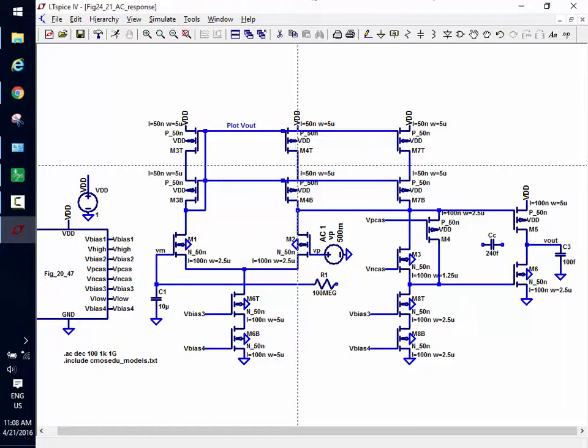No one's going to turn in this topology, right? Okay. So does everybody see sources tied together in both of these? Gates tied together, drains tied together. Sources tied together, gates tied together, drains tied together. Does everybody see that I have a gain from here to this node? And then I have a gain from this node to here. So this is my second stage gain.